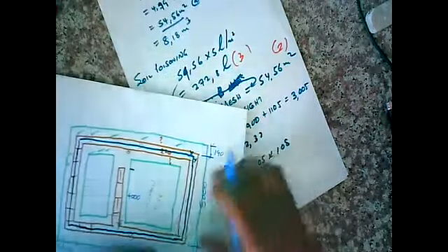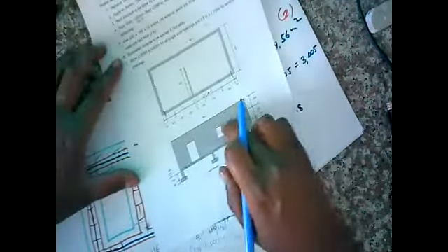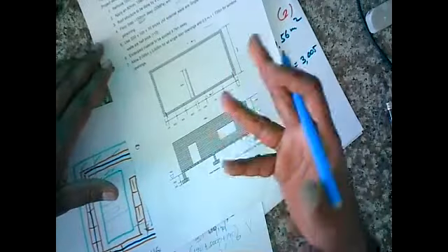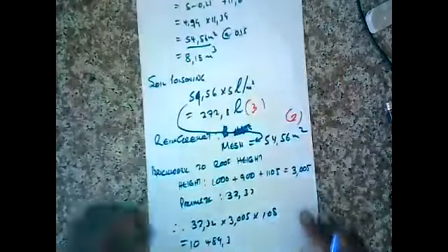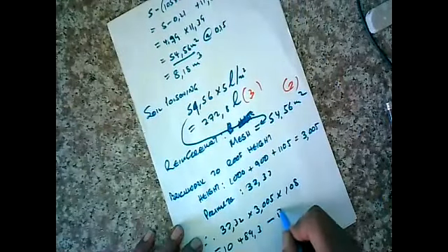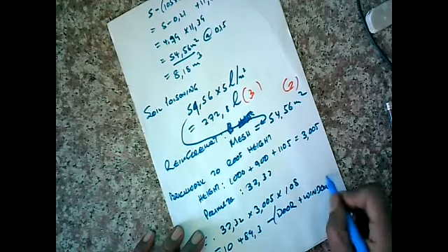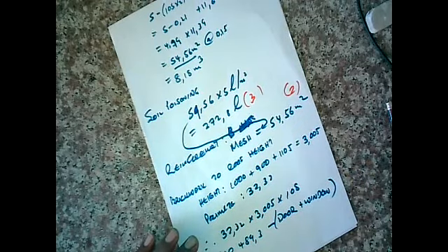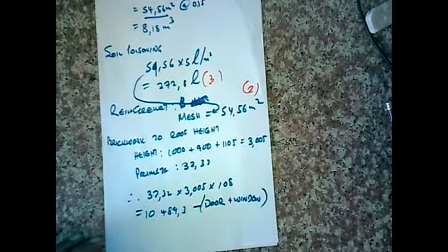What are they? The windows and the door. So we've got one window, one door. Now those don't take up bricks. You need to remove them. Let's put in here minus door plus window, so we don't forget what we're doing in our calculation. All right, let's move to another page.